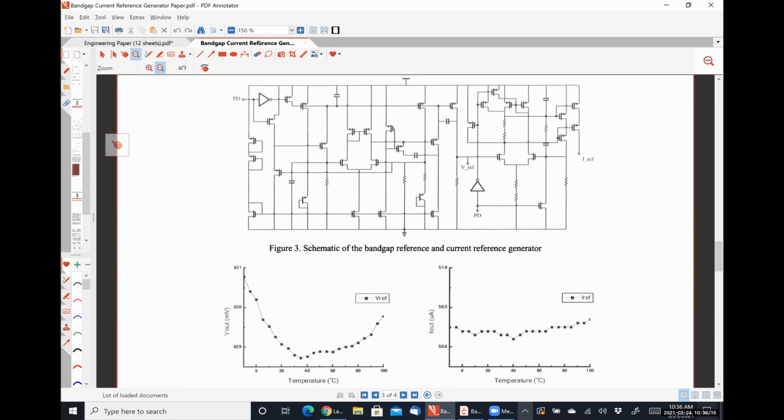We got a BJT and a BJT. So it is a mix of BJT and MOSFET technology, which means in order to design this circuit correctly, you have to intentionally include parasitic BJTs into your CMOS design in order to make this guy work. That isn't wildly difficult, but it is a bit of a pain in the butt.